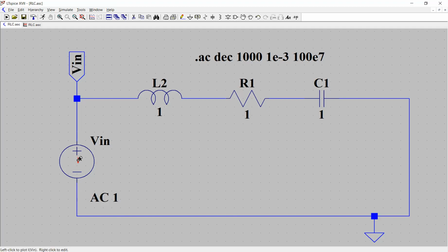But take a look at here. If we point at the voltage source, the current flow direction is from positive to negative, which is what we just understood. So SPICE actually computes it in a reverse direction. So when we plot the results, we have to take the negative of the current, right? SPICE shows that it is entering from positive to negative actually.